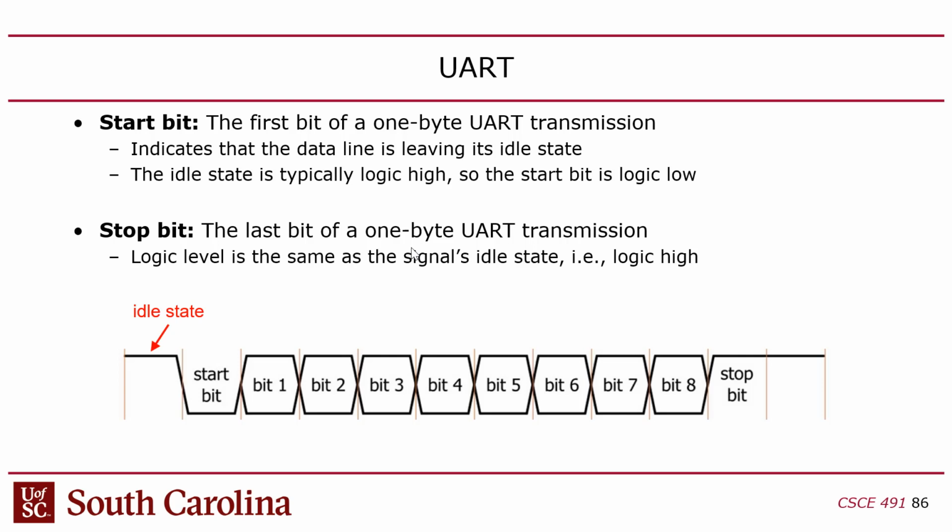Now there are two problems with this. Number one, if you're like me and you don't read manuals, you never know what the baud rate is supposed to be, so it's a trial and error process. Every time I connect a terminal to my FPGA, I have to try 9600. Does that work? No. 19,200, does that work? No. 38,400, does that work? I've wasted hours and hours of my life with this horrible trial and error where I'm trying to guess baud rates.